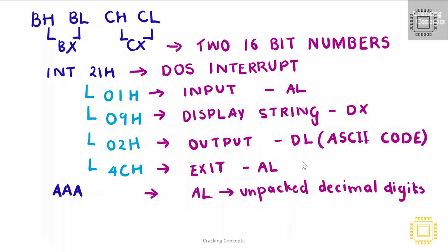When you observe here, we'll see that except storing the offset of string, all the other function codes use an 8-bit register. Due to the same reason, while performing addition, we'll be taking the register as bytes rather than 16-bit. That is, the lower digits of each number will be written to CL, BL, and the higher digit will be written to CH, BH separately.